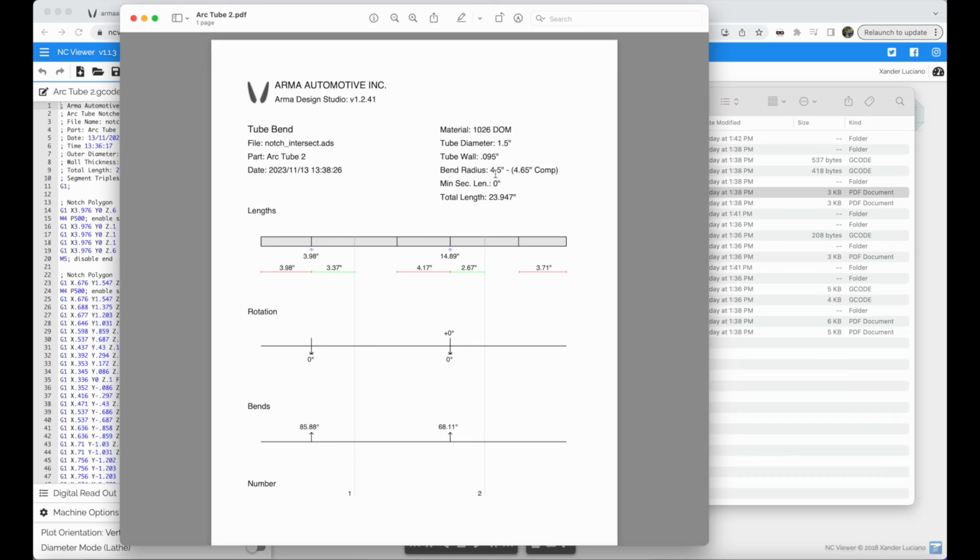It will bend, measure the resulting angle, and then do another bend that will compensate to result in this angle. So these coordinates on this file are compensated, so that where the bends start and stop is compensated so that this geometry of your CAD file is using the compensated bend radius, so that when your parts come out of the notcher and bender, they will fit exactly in the dimensions that you have in your CAD file.